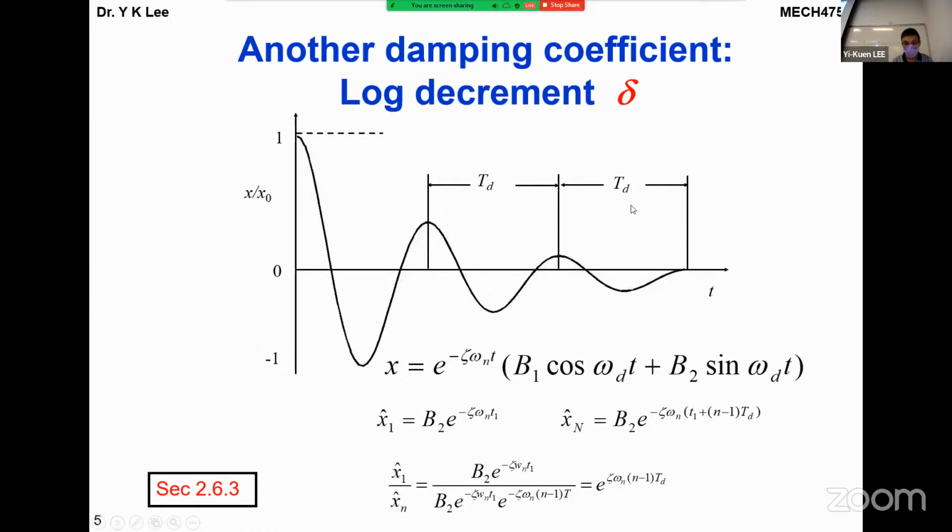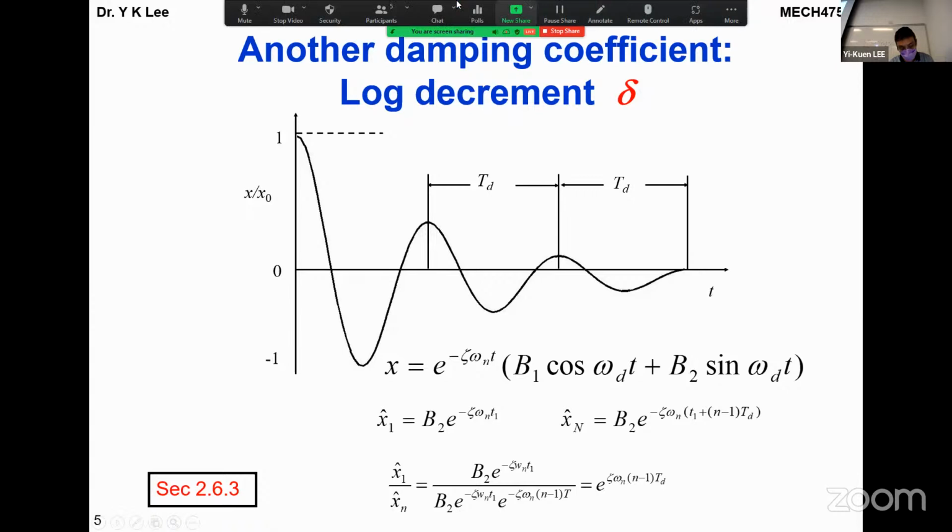Okay, and of course we already mentioned that if you want to do more carefully, first is damping, right? How can you measure the damping? One thing is if you can have a vibration sensor to measure the vibration amplitude as a function of time. Your smartphone has a motion sensor, right? If you can measure vibration, like the motion variable, as a function of time, then in this case you can easily get this result. So I do hope that all of you have installed some kind of smartphone app so that you can really get this kind of result.